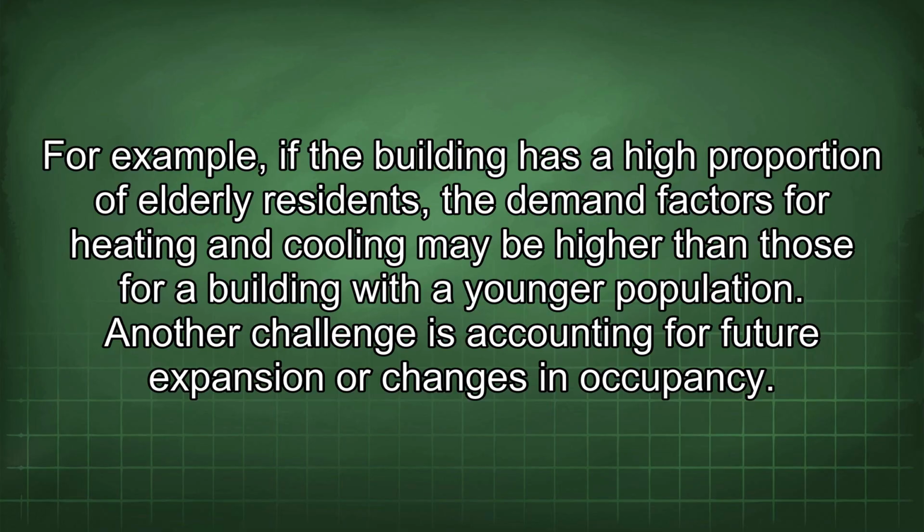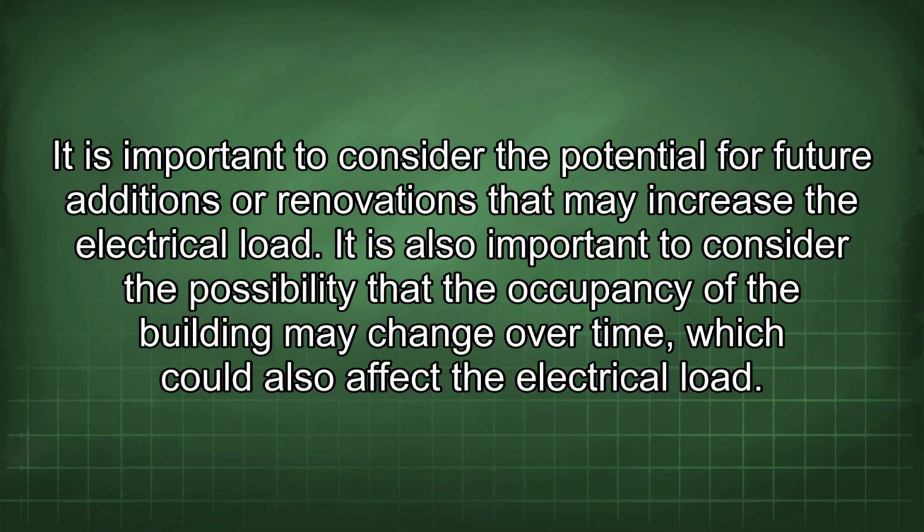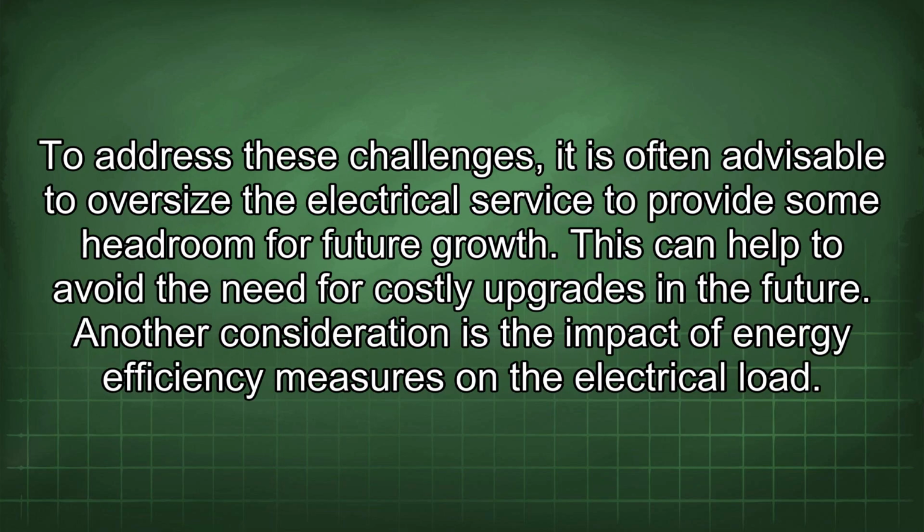Another challenge is accounting for future expansion or changes in occupancy. It is important to consider the potential for future additions or renovations that may increase the electrical load. It is also important to consider the possibility that the occupancy of the building may change over time, which could also affect the electrical load. To address these challenges, it is often advisable to oversize the electrical service to provide some headroom for future growth. This can help to avoid the need for costly upgrades in the future.